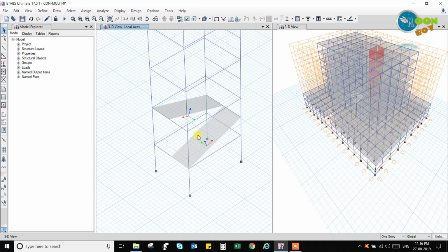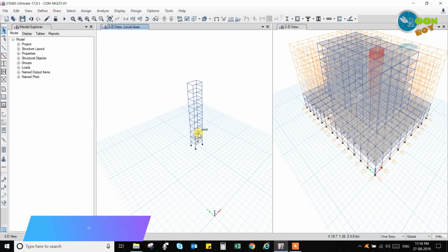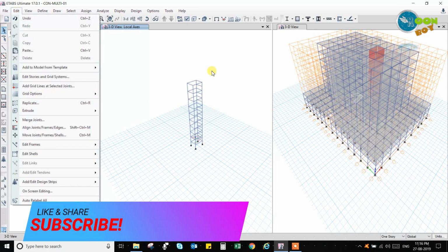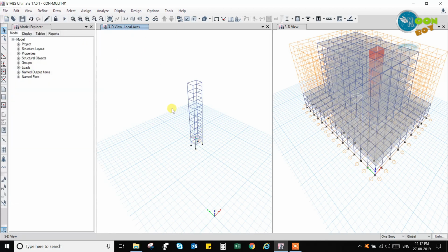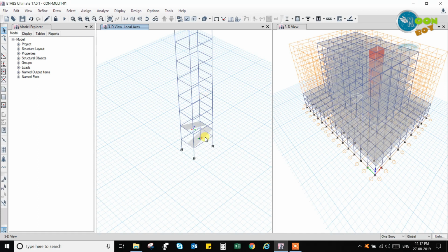Let us just start with this video. In this video I am going to show how to load the building and do analysis using this structure. In this structure I will change the diaphragm D that is none to D1 diaphragm, and I will make it a semi-rigid diaphragm so that I can show you what warnings come in this. And similarly, for the verification, I will show you how to clarify the warnings and how to get rid of them and do the analysis.